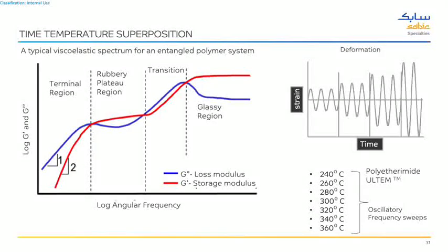At the processing temperature, it's more like a thermal regime. G prime and G double prime, as I told you earlier, are the storage modulus and loss modulus. I can also talk about viscosity, but I like to say storage and loss modulus because they say more about structure than viscosity alone. If we call it a thermal regime, that means you're on the processing side of things, and you don't see rubbery entanglement effects, more the segmental effects. But when you go close to Tg, which is 220 here, you get to see all the regimes, going from the rubbery to the glassy regime.